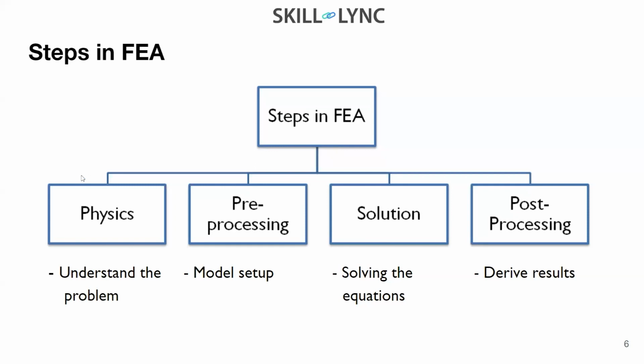Then after physics, you should have the pre-processing. By pre-processing, I mean meshing. Okay, so meshing and boundary conditions application. Meshing is one part of pre-processing. Then you have the model setup, so boundary conditions and everything you need to set. Okay, then once you have done this, you will ask for solutions. Once you get the solutions, you are going to check the results, right?